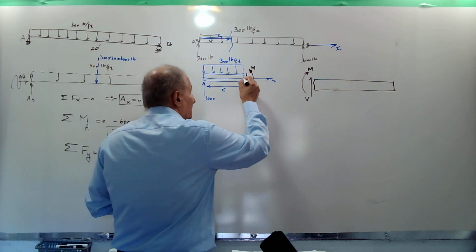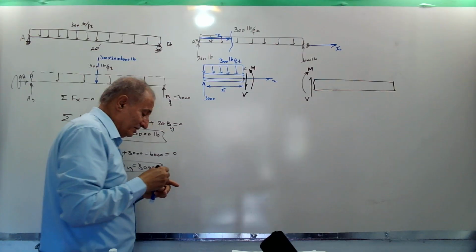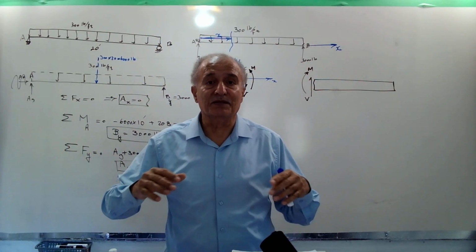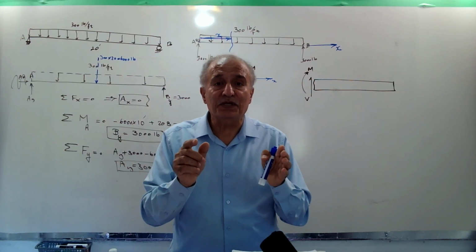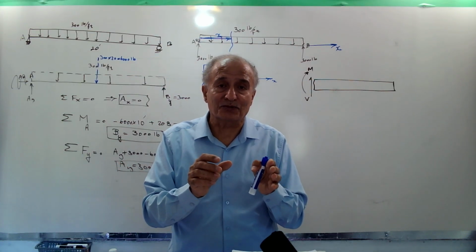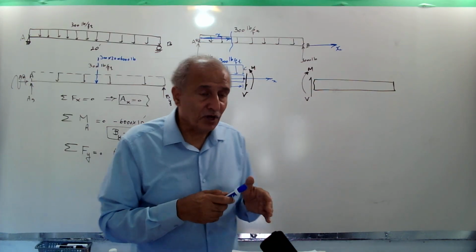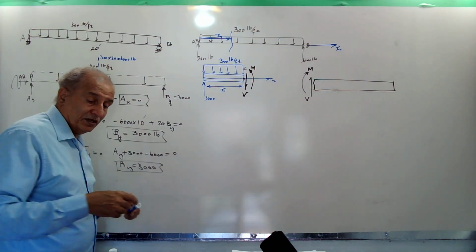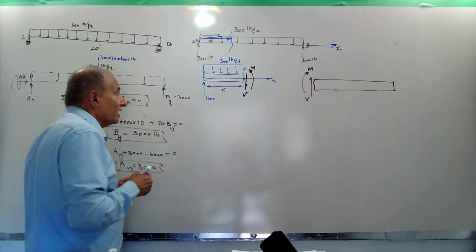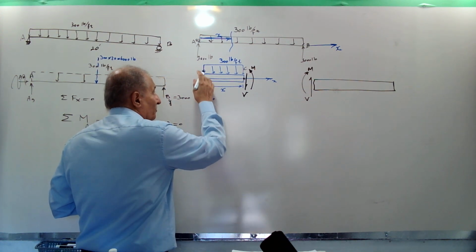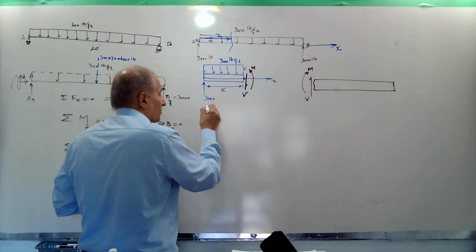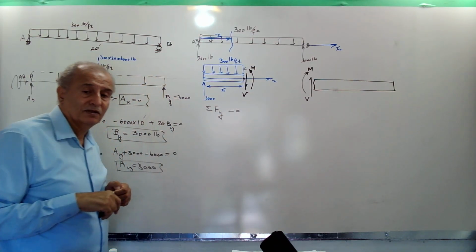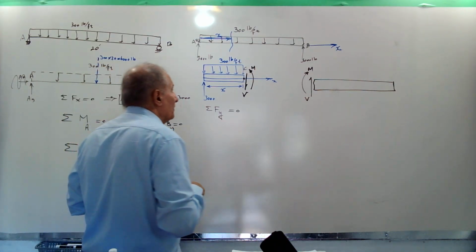Okay, let's write the equation at C, the cut section, equation of equilibrium. We know from statics, if a whole beam is in static equilibrium, any piece or portion of that must also be in static equilibrium. Then I write these equations again for this portion. I started from summation of Fy because I wanted to find out force V, shear force V.